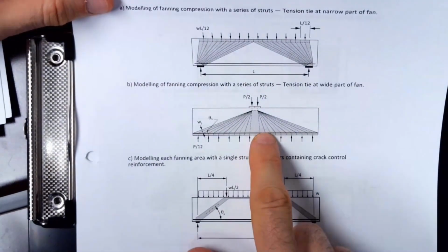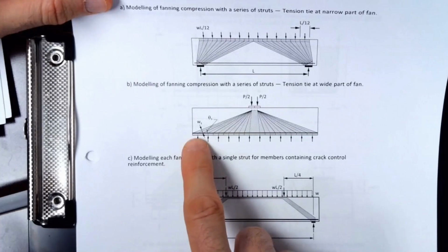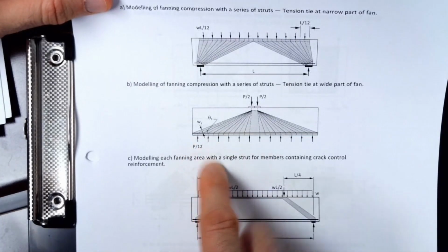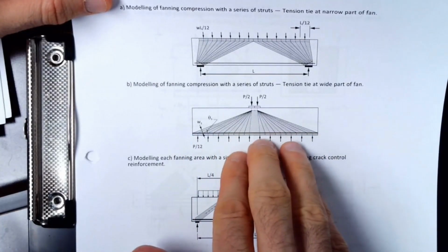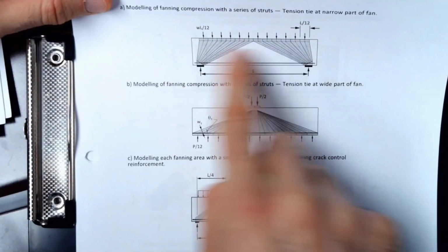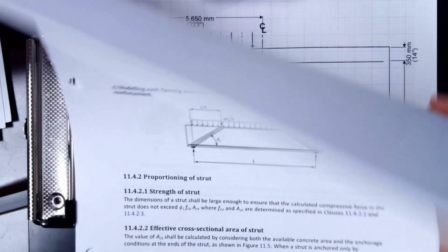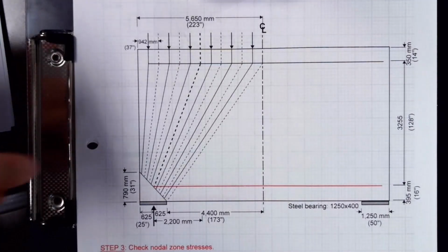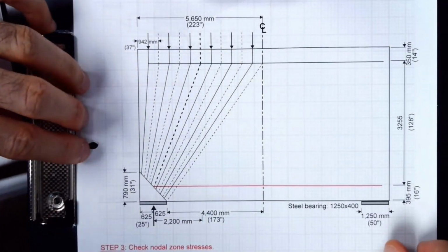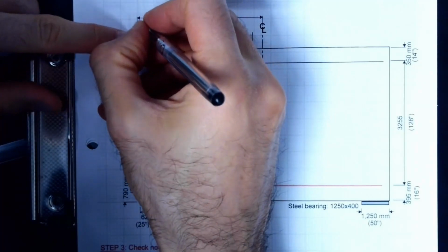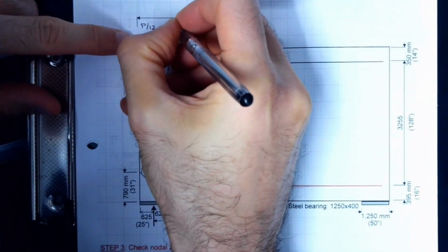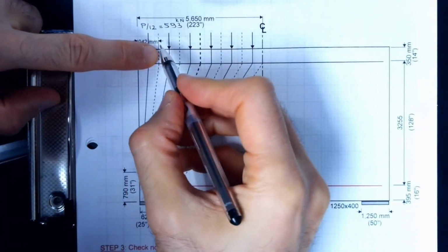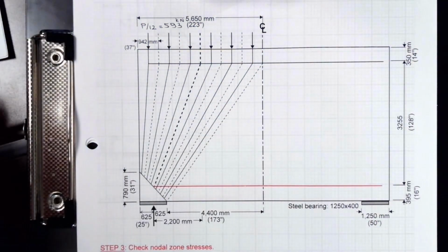The same approach applies to a foundation. So it's again, in a foundation, P over 12. So you do this separation. Again, you separate the load to various nodes. That's another one. So let's go with this one. So P over 12, that's going to be the load. You can definitely use AutoCAD. 593 kilonewtons. So each of them would be 593.